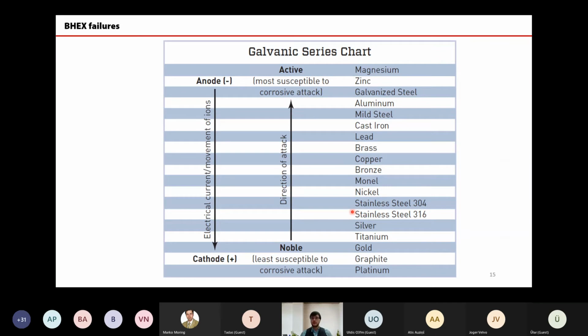So here I have two accumulated effects. First, I need to make sure my water is not aggressive, or my brazing material is somehow resisting this aggressive water. And second, I need to select my valve properly, not to lead the domestic hot water system to a thermal oscillation mode. That means I need to consider carefully my surface margin impact on the behavior of the heat exchanger and real flow rates in winter, and use these flow rates for designing the valve. And on top of this, of course, I need to double check if my capacity of domestic hot water is selected properly.